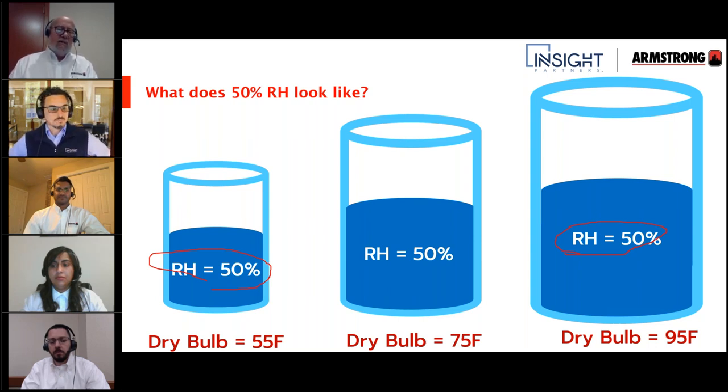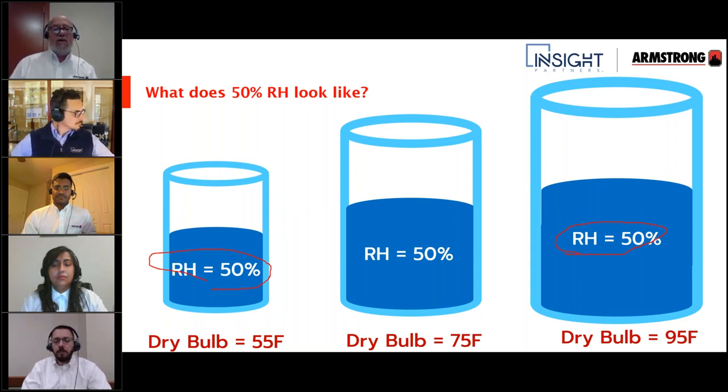I can use some of this information to help figure out whether I've got bypass problems, whether I've got airflow problems, whether I've got water flow problems, or whether I've got water temperature problems. All these things play in together to give me a true picture of what the air handler is actually doing.